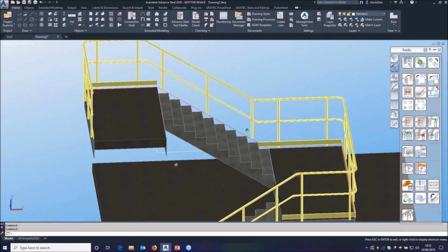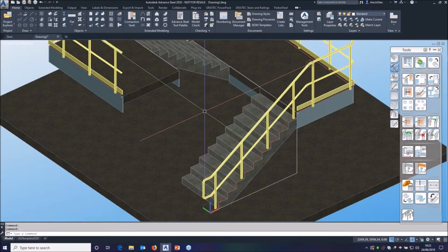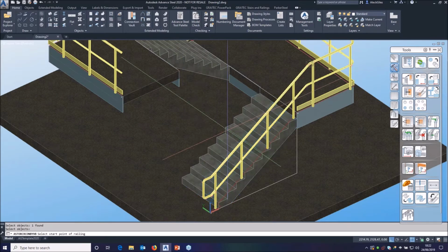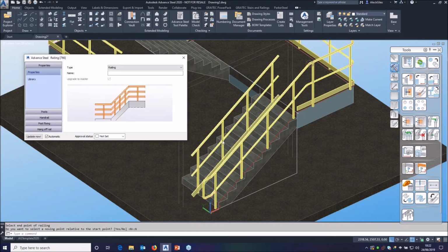Now we're going to do the inside rails. So again, similar really, they're still pretty easy. So I'm going to start with the rail macro. I'm going to put it on this beam, and again use the nosing line, system line of the beam as my points. Don't need the reference point. Comes up in the middle again. This time I want it on the other side, of course. I'm going to bolt this one on top, so you see two variations. So I don't want to go all the way across, I only want to go 50mm margin on the edge. So that's 550.